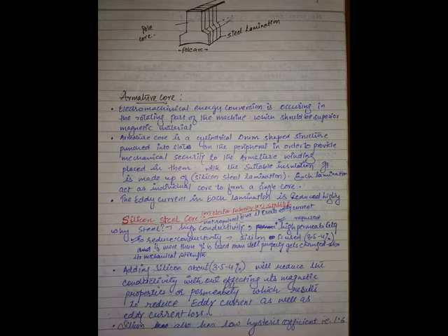If you have Z number of conductors, and Z by 2 are the coils, how many segments will you have? Z by 2. That depends on the question. Is it clear? So the number of commutator segments is always equal to the number of coils. Commutator is nothing but the image, the reflection of the winding inside.